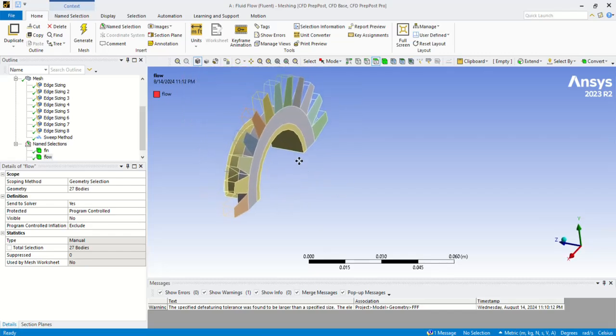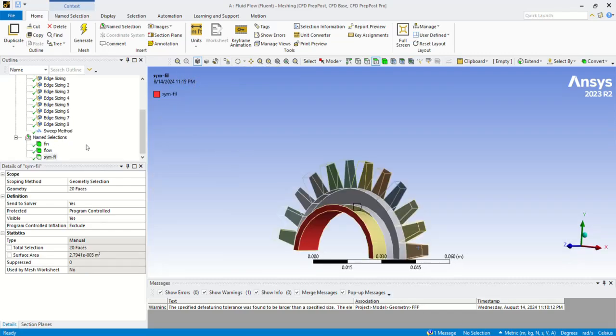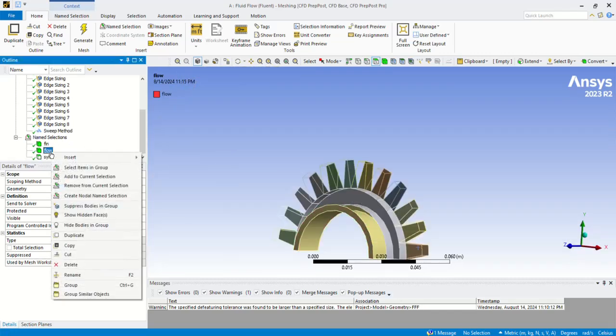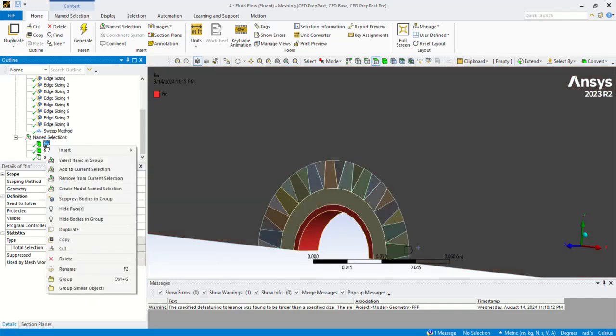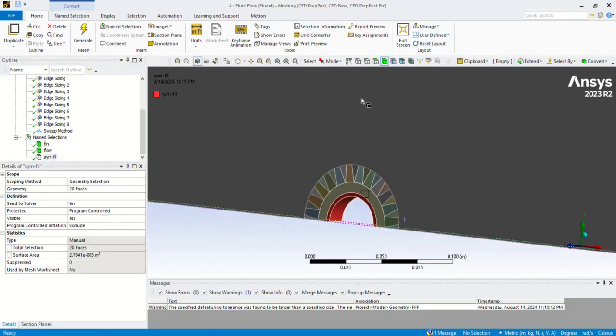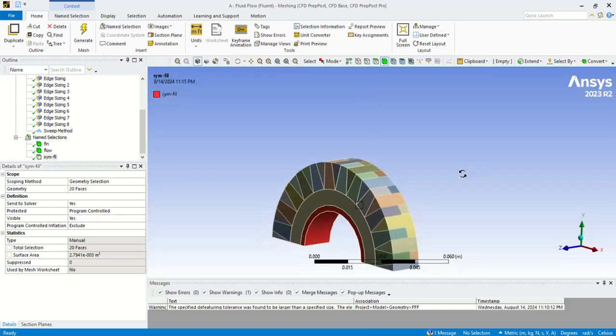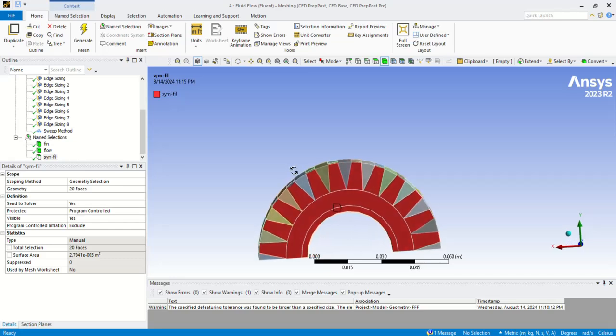Now we should select the wall boundary condition of the fin. We select show full body of the fin. For this we show, and again hide this body with the F9 button. It is a shortcut for hide. Also select this and hide the domain part of the body.